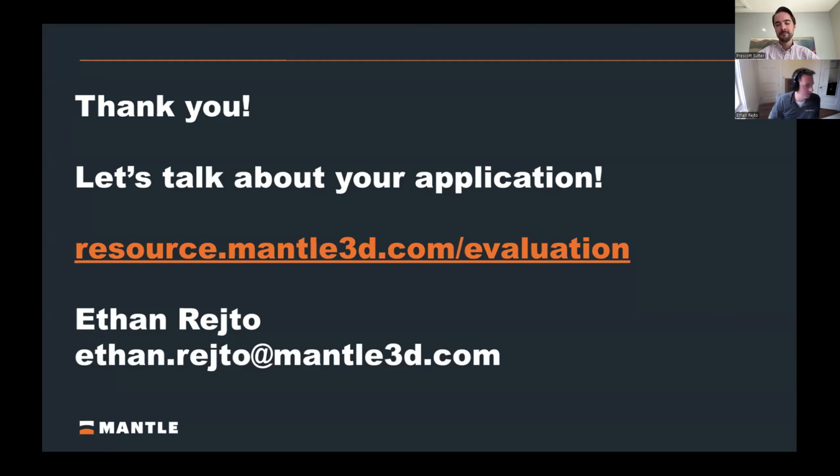Great. First one here asking, can we recover a build if there's an issue, a power outage, etc.? What happens then? Yeah, absolutely. Unlike a lot of other technologies, it's pretty straightforward on the printer to face back. That's the advantage of building your equipment on the backbone of a vertical machining center. We've got a functioning CNC machine that we can use, so it's easy to dock back, machine back, and start your build at a different height. So there's no impact to your build quality or fidelity if there's a power outage or disruption.